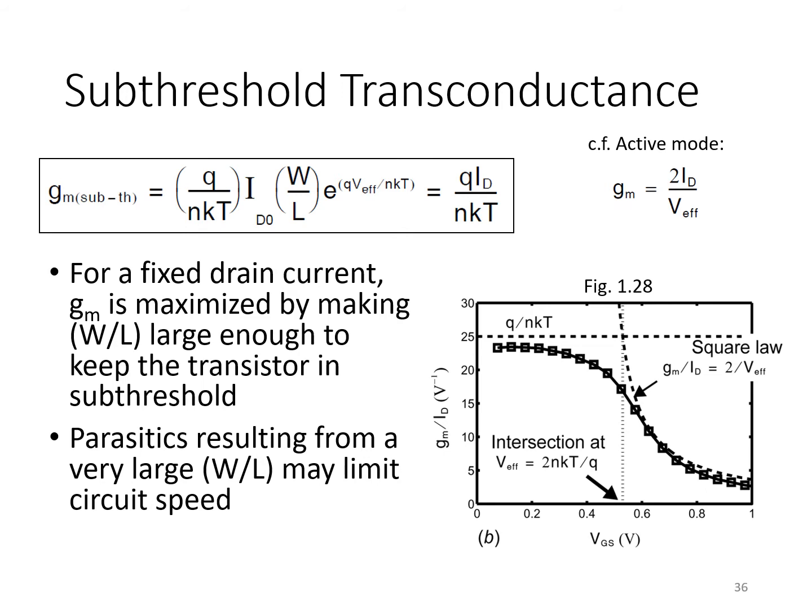So the relationship presented here is actually plotted for an example transistor on this plot. Here we've got the ratio GM over ID. So we take ID, move it over to this side of the expression, and what you're left with is a plot of 2 over V effective.